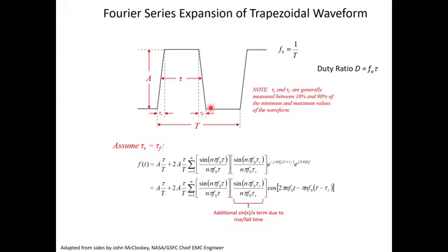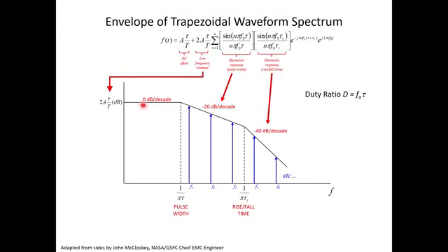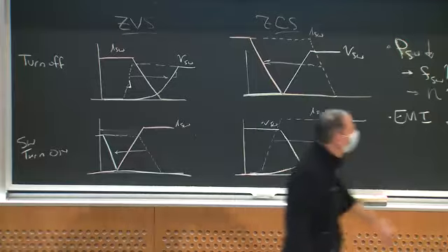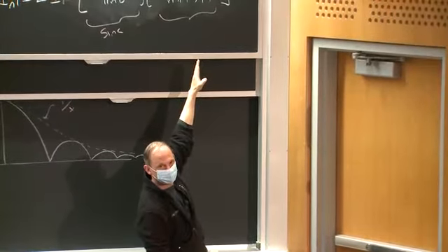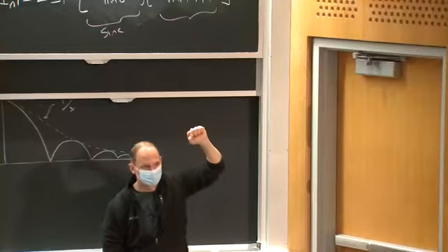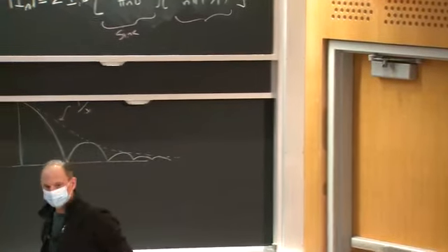So here's what happens. From the original square wave, I get something that starts off at DC and then falls at 1 over f. And then at higher frequencies, I get this additional attenuation of another 20 dB per decade, and that's because of the roll-off of the second product of the sinc function. Make sense to everybody? Yeah, Laurie?